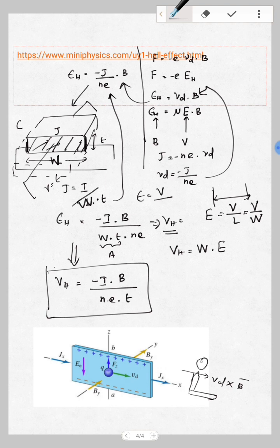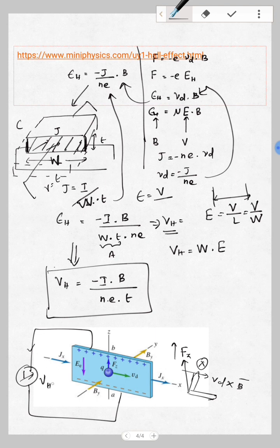We will take it as always a cross. I think you know that for a magnetic field going inside, the back of the arrow will be a cross, and the cross product of these two is nothing but the force acting on these holes. It is towards the top, so the holes are forced to go to the top, so electrons will naturally be at the bottom. If we take a multimeter and measure this, the conventional current direction is this side, so the reading will go in one direction. This will give me the current, and through that I'll find out the voltage.